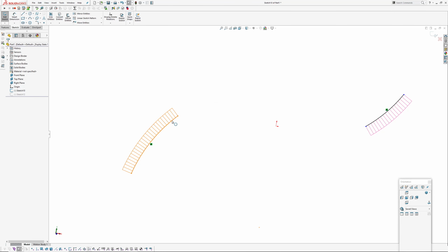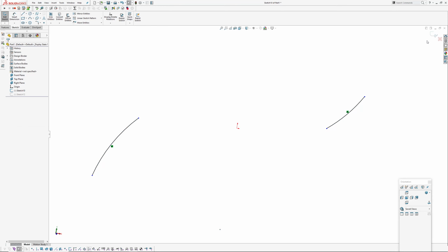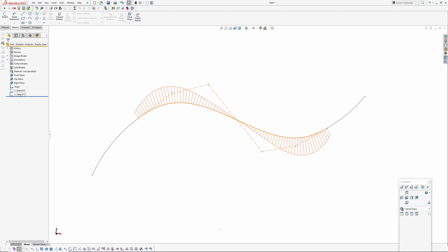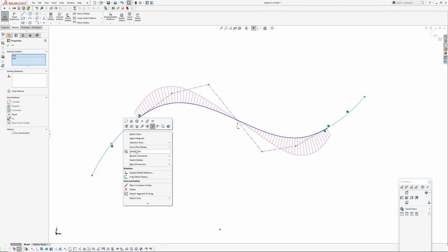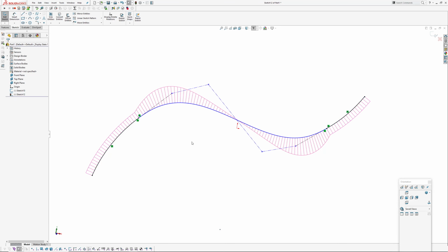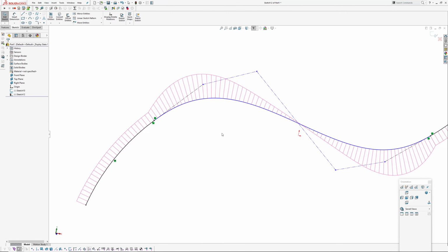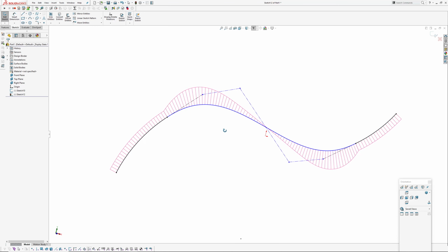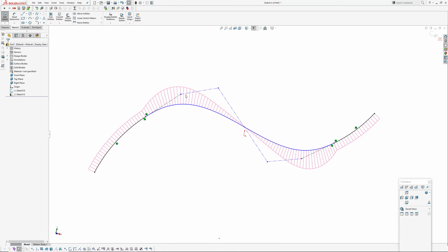We'll just pop over to this sketch, turn off curvature combs, go back into this sketch, I'll convert entities and then turn the curvature graph on for these arcs. Okay, hey presto, problem solved. So that was a different scale for the curvature graph in each sketch, even though I didn't change the scale. It must just automatically change it.